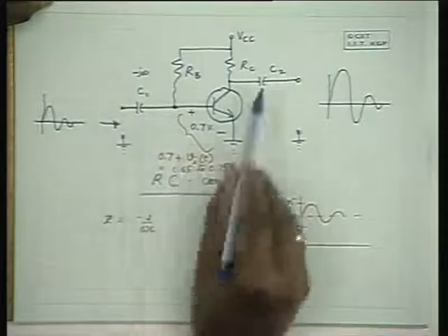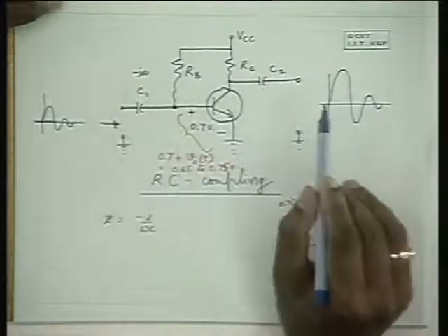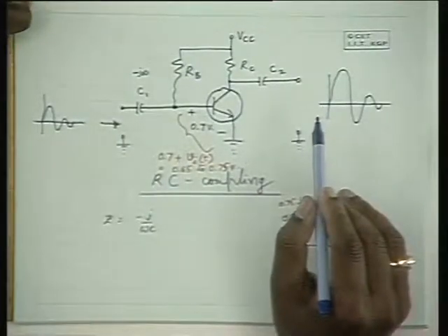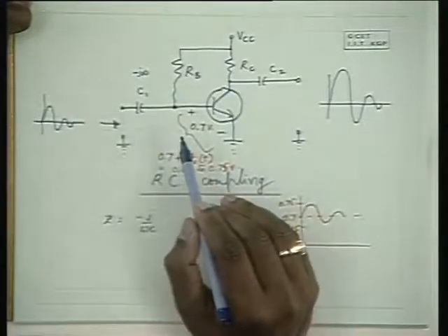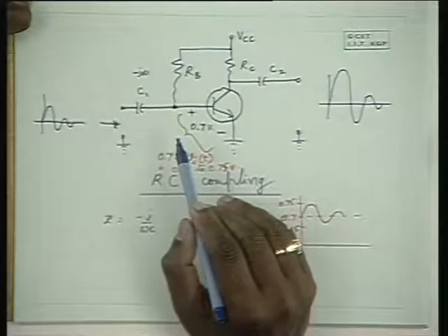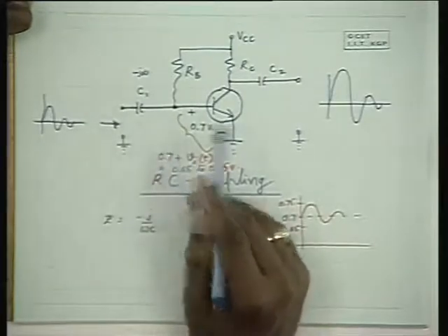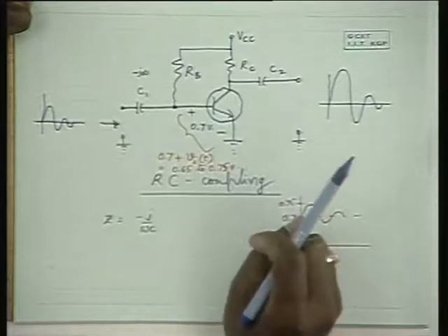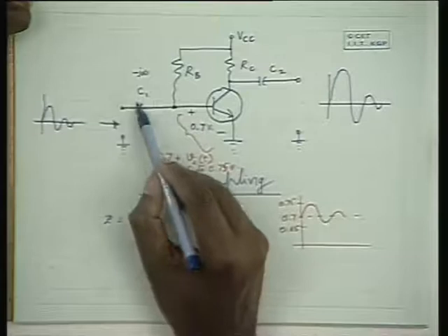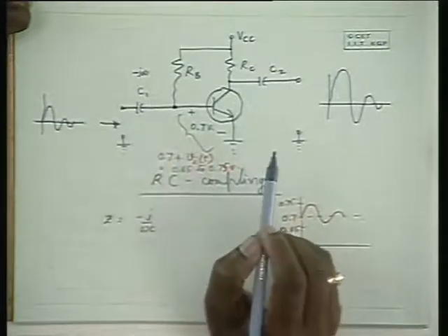Amplifiers which use capacitive coupling are known as RC coupled amplifiers. Naturally, they cannot be used for amplifying DC signals or low frequency signals because the capacitor blocks them. So we do have DC amplifiers or very low frequency amplifiers wherein we don't use a coupling capacitor.